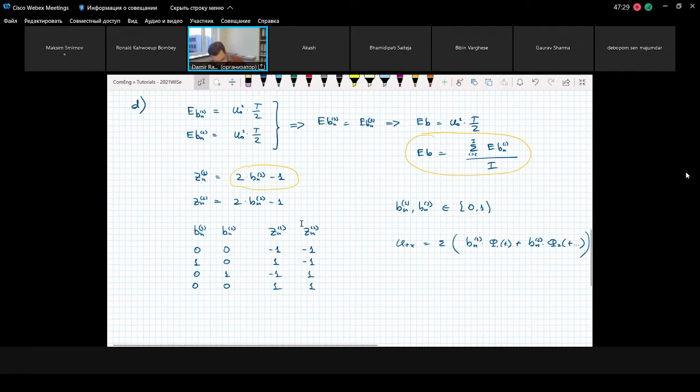And now we come to the discussion of signal space. There are 4 possible constellations of the bits b0^(1), b0^(2). Therefore, we can also distinguish 4 possibilities from s1(t) to s4(t) for the transmit signal u_TX(t). And then we need to sketch the signal s_i(t) for i from 1 to 4.